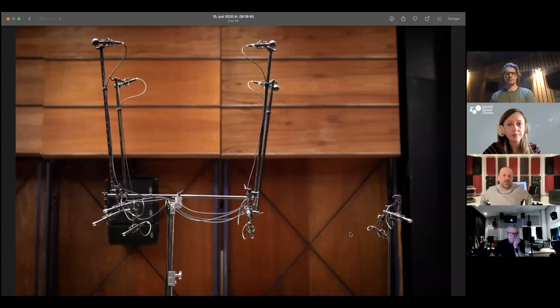There we go. That would be my typical microphone array, picking up what's happening. And as you might see, the configuration of the microphones mimics a miniaturized version of a 7.1.4 speaker layout. So with this microphone array, we pick up the same intensity and time of arrival that the speakers would release in the playback environment.